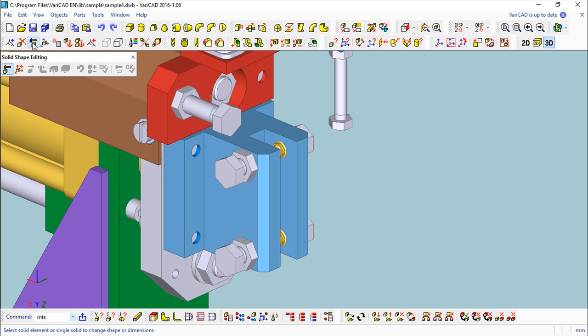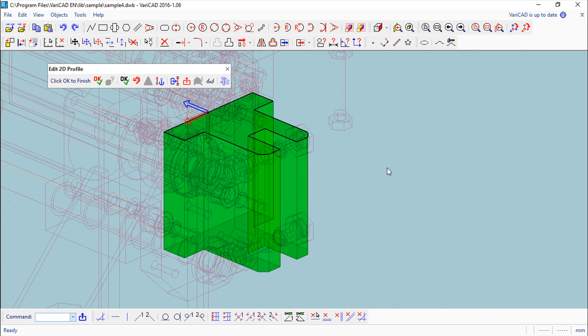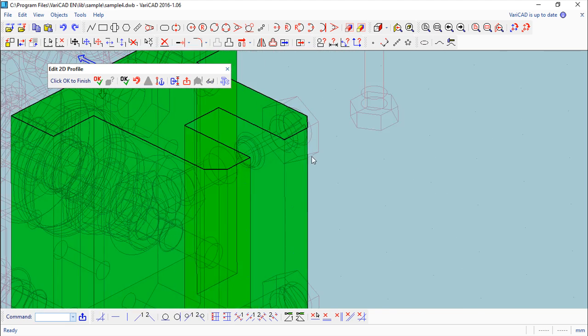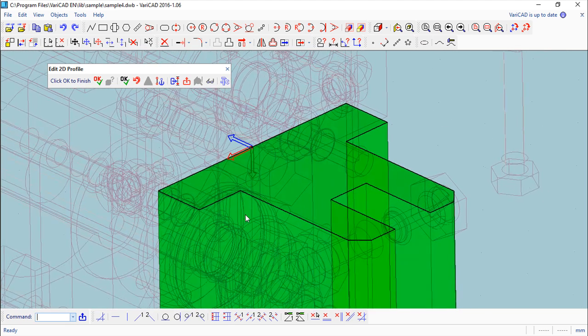Go to the same function, and I'm showing now the second group, called the addition of solid element shape. So I click on a solid, it recognizes the profile that was the base for the solid. So I can click it, confirm, and I get this sketch mode that you already know.